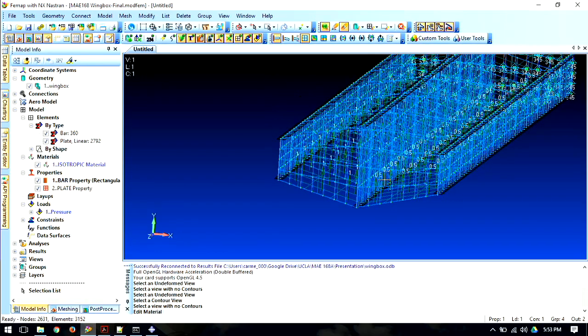This is just, for what we do, we don't generate our loads. There's a different loads group, so they generate loads for us. So we build our finite element model. The loads group creates loads based on not necessarily CFD, but they have other software, simpler theory to come up with loads. And they produce those loads based on what mass properties feeds them. Mass properties has to track all the weights, so you need your weights, you need your inertias of your aircraft to be able to predict the loads, and that's the cycle that they go through. Then they produce loads and give it to us after we give them our FEM so they can apply the loads. And then we run our analysis. So the applying loads portion you don't really do, at least in a big company where every group has their own job function. You might do it at a smaller company.